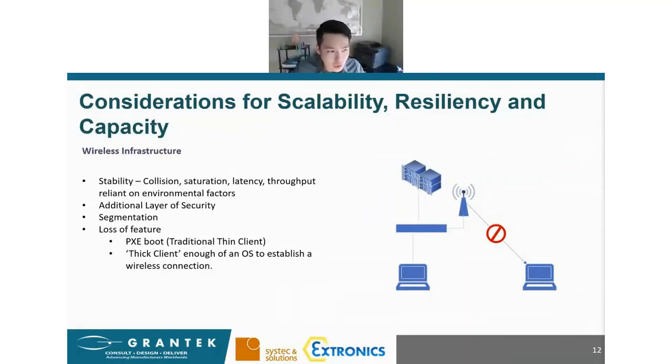People also have some concerns over loss of features. Something like traditional thin clients that communicate and are provisioned through PXE boot may not work anymore once you're talking through wireless. There are solutions out there, though. There's thick clients with enough of an OS to establish that wireless connection. So one popular one is IGEL, which is Linux-based and it's secure and it allows you to connect the terminal to a wireless network, much like something that would run Windows, but you don't have to pay for the full-blown Windows license for your SCADA application.